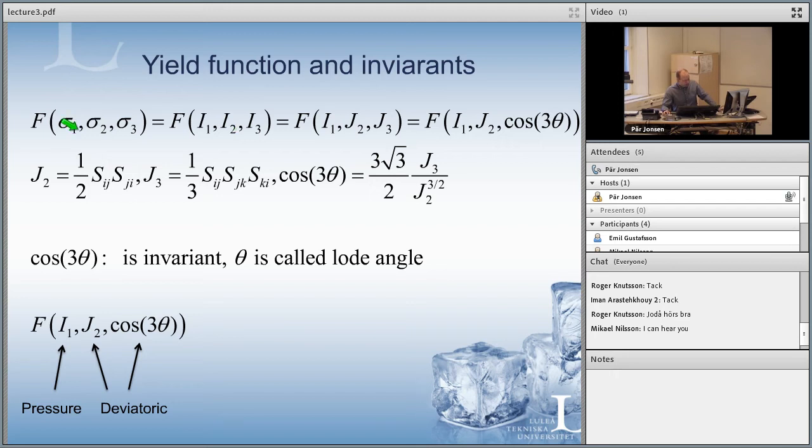Usually for steels you can simplify it a little bit. But nowadays you can see this Lode angle dependency coming in. You have the triaxiality. For example, if you have cracks, in front of cracks you have a lot of triaxiality depending on the thickness of the material. Then this Lode angle can be very important. Also, if you have anisotropic behavior of the material.